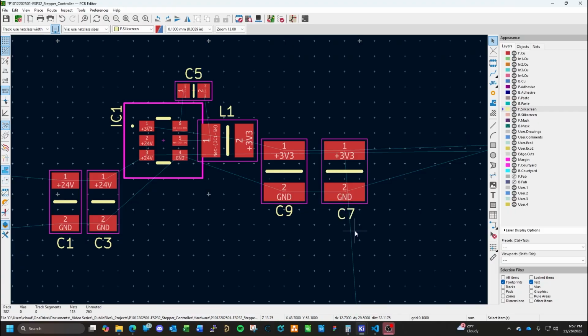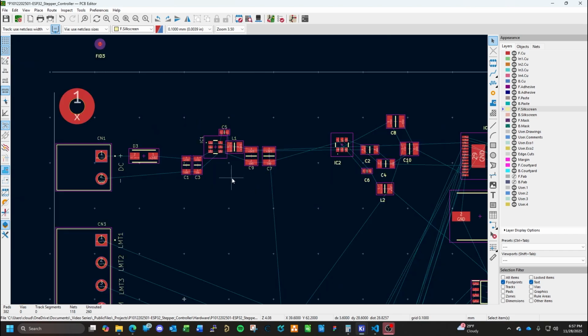Now, one of the things we've got to keep in mind is we're going to be hand assembling these. And another thing to keep in mind is repairs or rework. Sometimes if you overcrowd your parts, that makes it too difficult to make repairs or do rework to solve for future issues. Typically, you don't have to worry about that, but during the earlier prototype phases, it's something you might have to, but you aim not to.